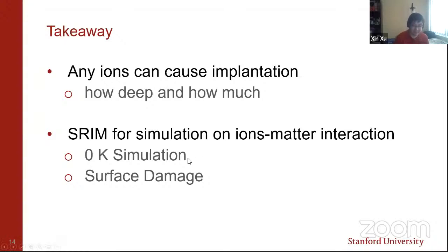So it also points out that even if you are doing cryo FIB, you are still seeing this implantation. The cryo FIB cannot make the sample surface pristine. It can only reduce the damage due to heat, or due to bad heat dissipation.